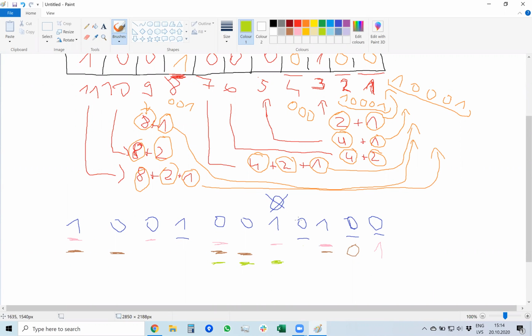So let's calculate parity bit number 4. 1, 0, 0 tells us that we should have an additional 1 to make the number of ones in this subset even. So this parity bit is 1. And we see that we received 0. It should have been 1.